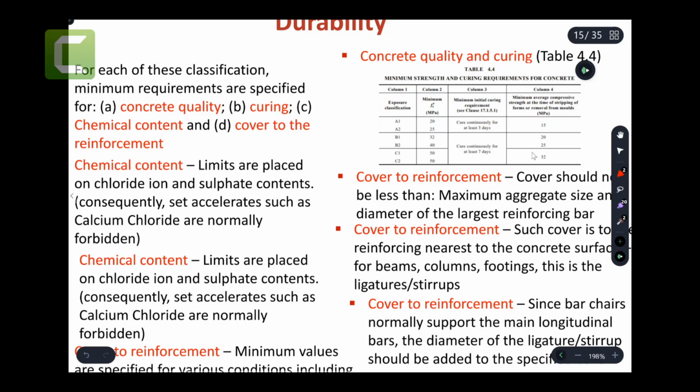In summary, as a designer, what you're going to be asked in test 1 or 2 and the final exam, we will ask you in one of those exams to design for durability and shrinkage and also fire, which we're going to talk about in the second half of today's lecture. Mainly what you're going to be doing is finding the correct cover and ensuring your adoption of the correct strength, the MPa that we talked about last week, and also using the cover.